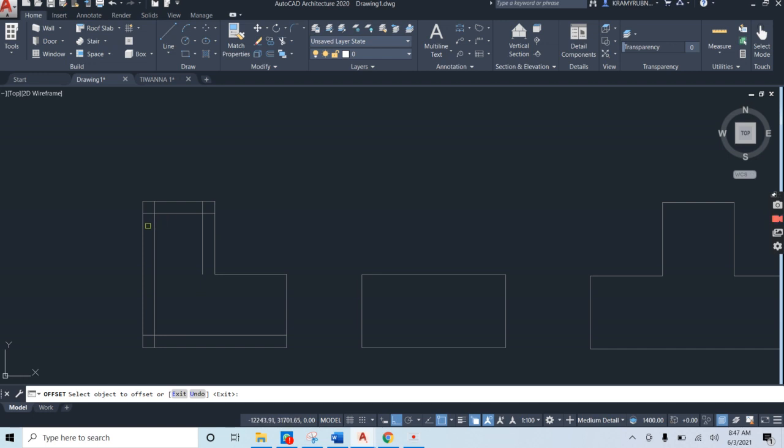By virtue of the steels being bent, the corners of our links are required to have curves of radius 13. 13 happens to be the size of our steel bar, so I'm going to give fillet with radius. Select radius from your command area.